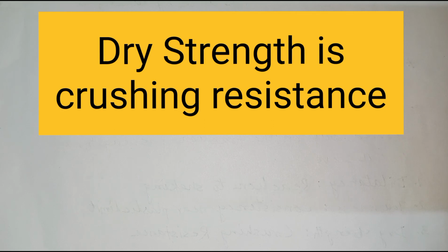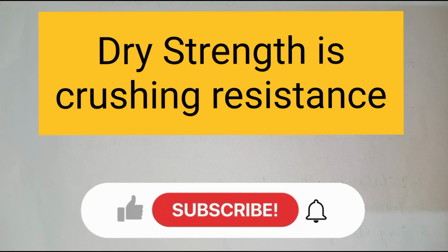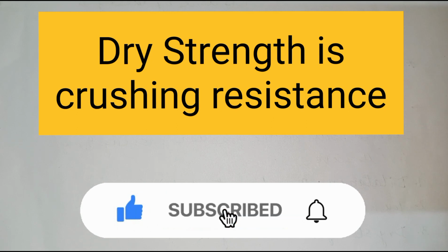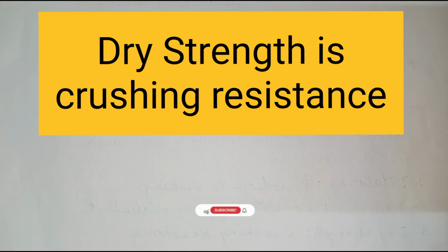A high dry strength is a characteristic feature of clays of high plasticity. Typical inorganic silts have only a slight dry strength. Silty fine sands and silts have practically the same low dry strength but can be distinguished from each other by their feel during powdering of the dried sample.